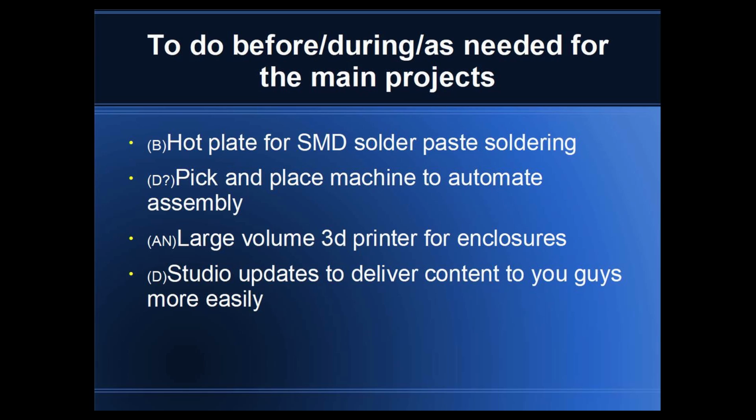Then once all the components are placed, you can just pick up the board, put it on the hot plate, set it for its program, and it'll solder everything up, and it's all said and done. Something I'll probably need to do after that is testing solder joints and make sure everything's okay, but that can be another project down the road for whatever we're working on.